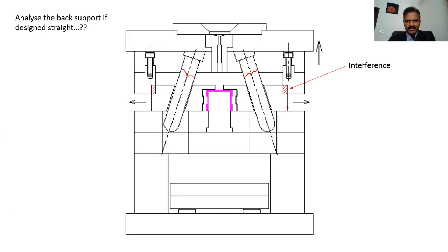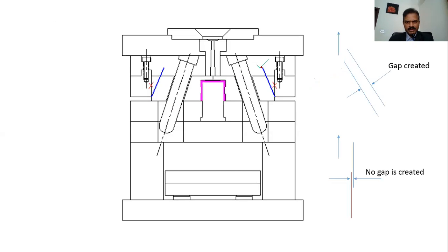So we have no choice. Instead of making it straight, we have to design the tail end at an angle. And what this angle is, is a question which we should comprehend thoroughly. So, the popularly used, scientifically proven angle for mounting the finger cam is 15. Sometimes there are cases you can move it up to 18 or 19 degrees depending on the requirements, but commonly we use a mounting angle of 15 for the finger cam.